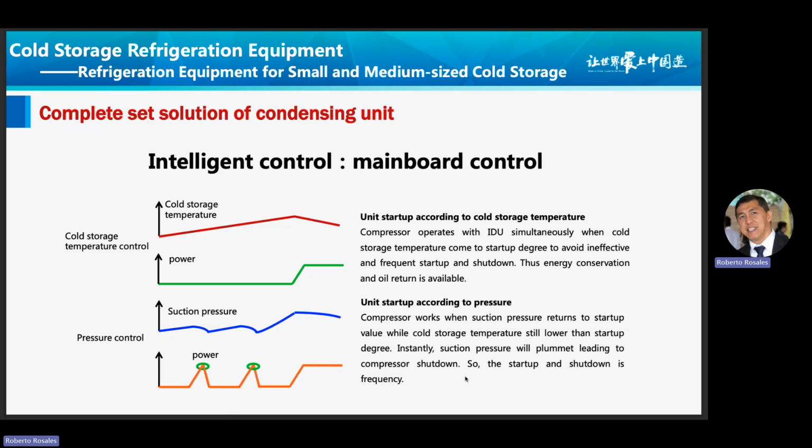It has features also for intelligent control wherein the main board unit starts up according to cold storage temperature. Compressor operates with indoor unit simultaneously when cold storage temperature comes to startup degree to avoid ineffective and frequent startup and shutdown. Thus, energy conservation and oil return is available.